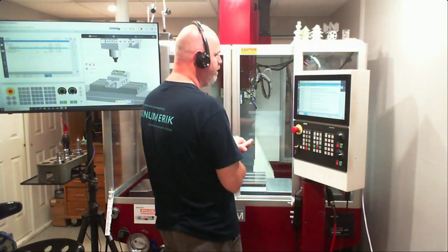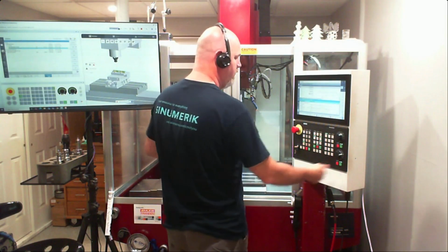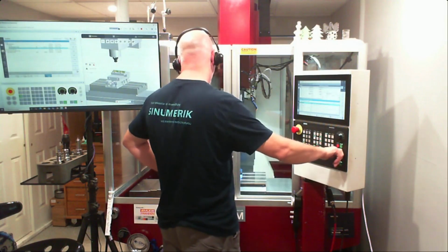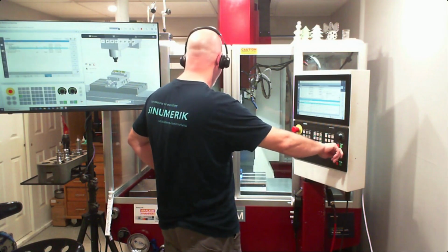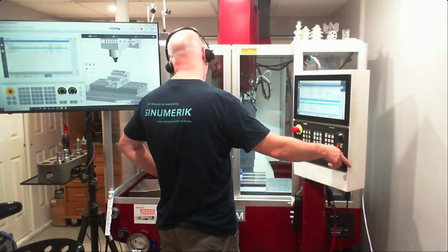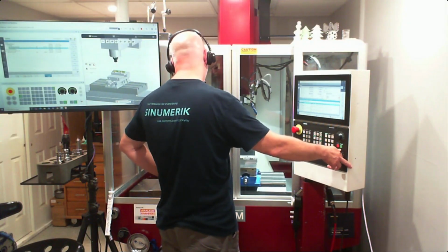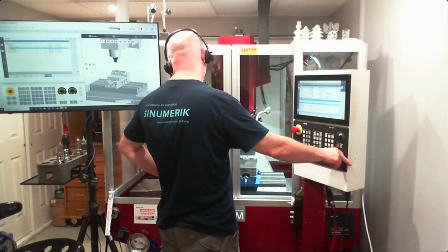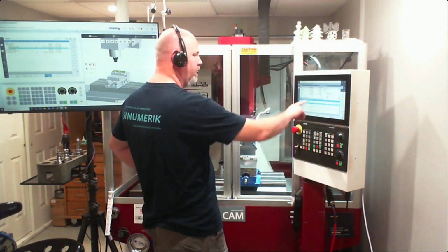So I'm going to jump over to execute, and we'll always, always, always, I don't care who you are, if you're going to run a program that's never been run before without cranking it down on the override, you're going to crash your machine. Maybe not today, maybe not tomorrow, but it will happen. So I always like to just double check, make sure everything looks good.